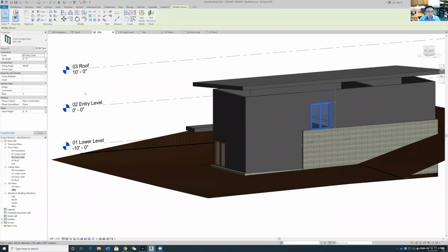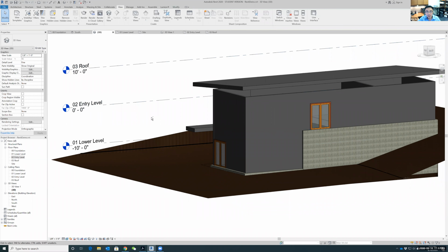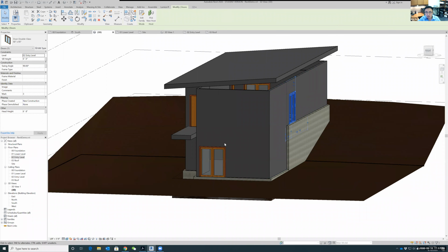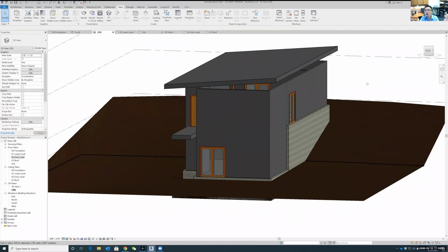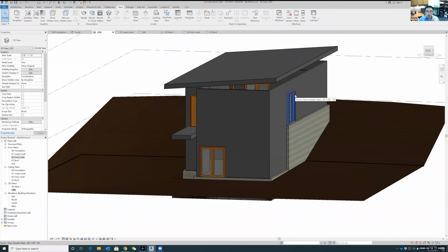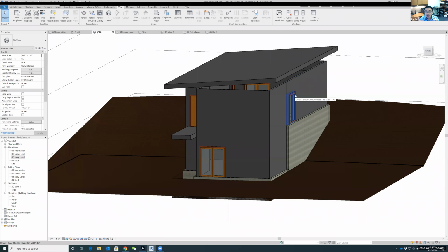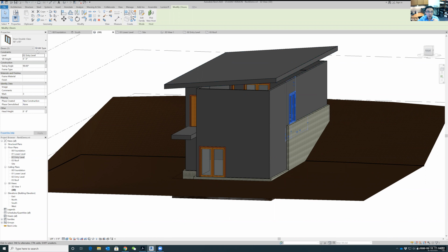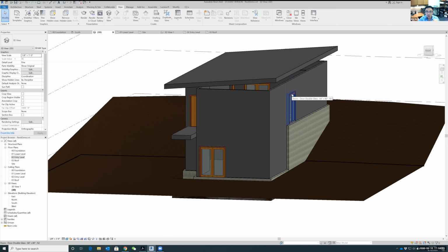Yes. If you select this door, you'll notice there are so many parameters that you can change, like this is a 68 by 80. But the problem, and this is very important, guys, is that when you change this one element, you change every single element from the same category. This is how Revit controls the information. These are just instances of the same type. So if you edit this element, you would think you are just changing it, but actually you are changing the entire type of doors. We don't want to do that, but we can still work around it.